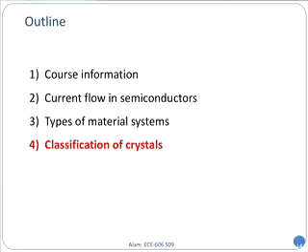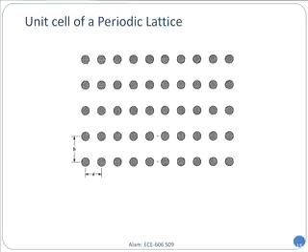And classification of crystals. So this is a periodic array of points. It could be ions, for example, atomic ions, but for this case, just assume that these are geometrical points, an array of geometrical points. Shown here in 2D, it could also be in 3 dimensions, in a periodic array. Now, how will you build it up? It's an infinite array, so one way to build it up is to have a unit motif of a rectangle shown here in yellow, and you can see 1/4 of each corner point is included in the yellow. And you can repeat this and build up the whole crystal.